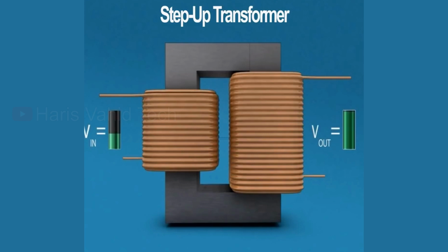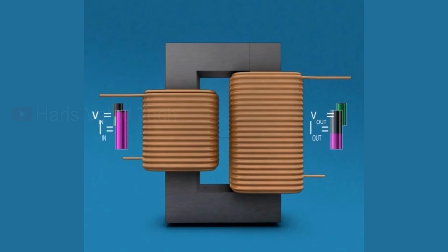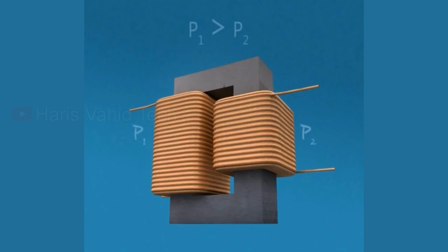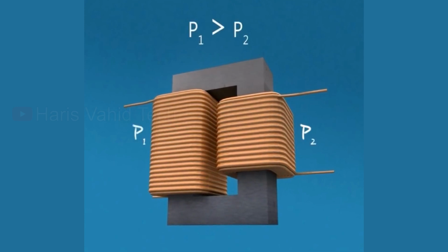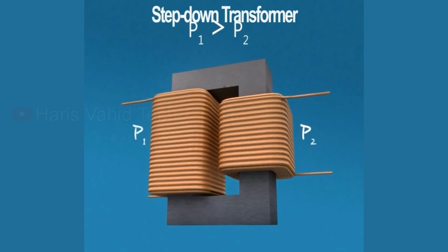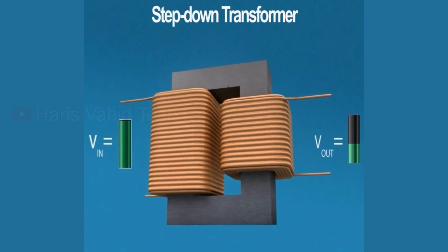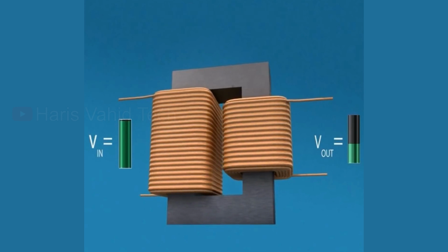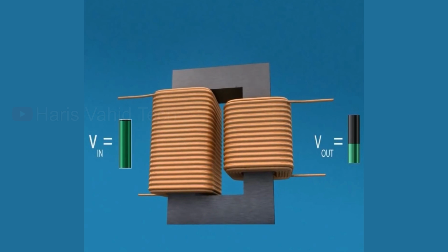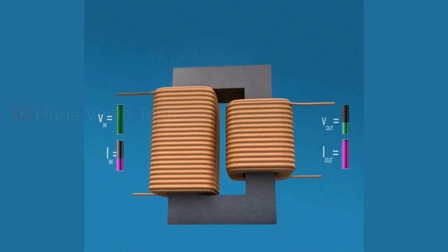All types of electrical transformers used in electronic circuits basically consist of two inductors. One of these inductors is meant for supplying alternating current from an external source and is referred to as the primary winding. The other coil, in which the voltage is induced, is known as the secondary winding. If two coils are placed near each other, the change in flux in one coil will cut the turns of the other coil and will induce a voltage in it. Then these two coils are said to have a mutual inductance. In the previous video, we already discussed mutual inductance.